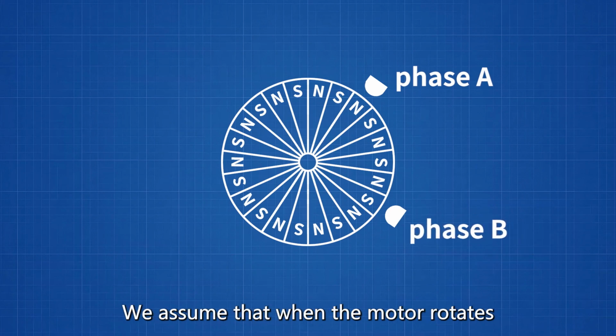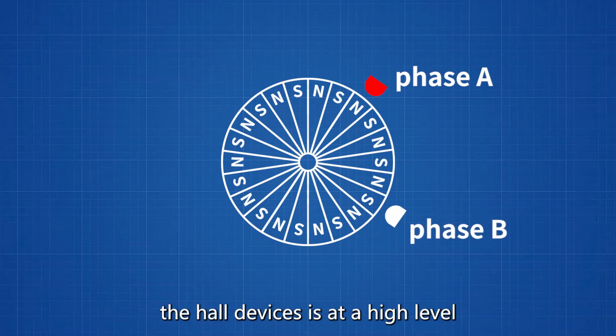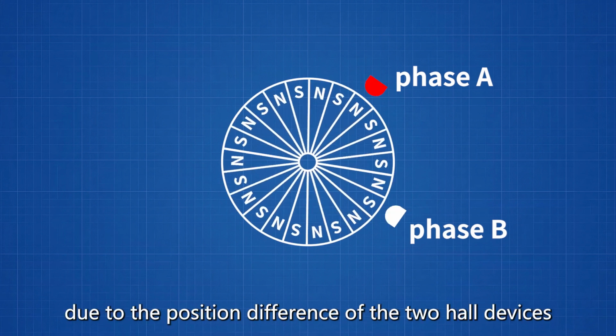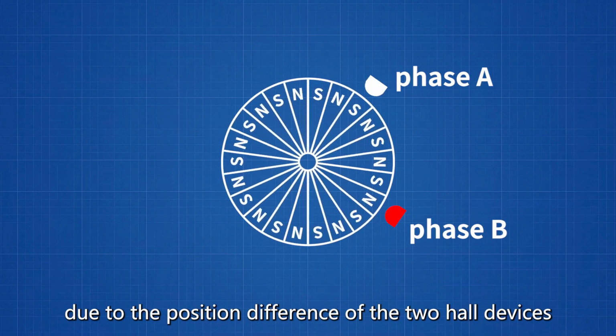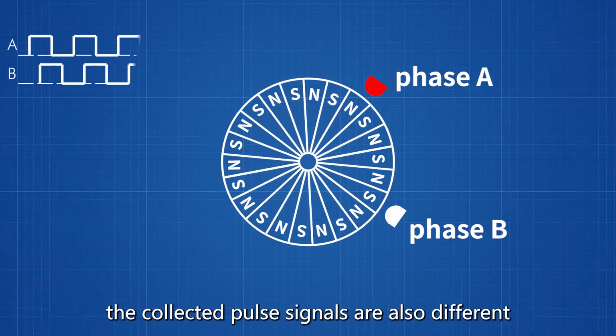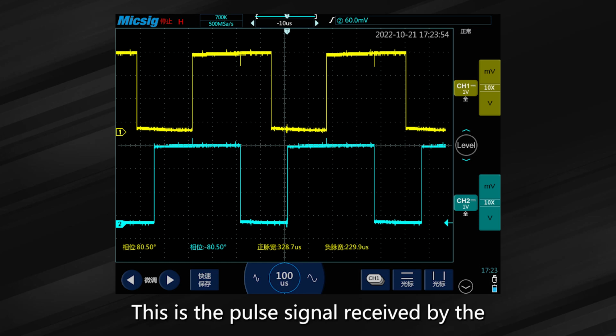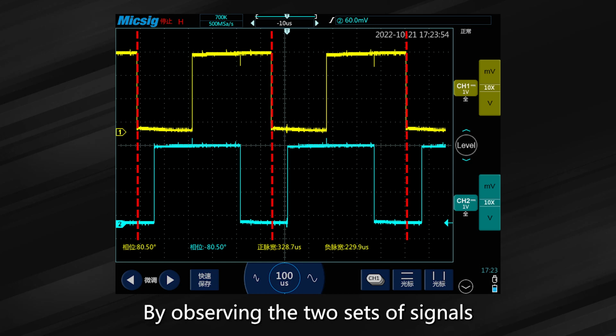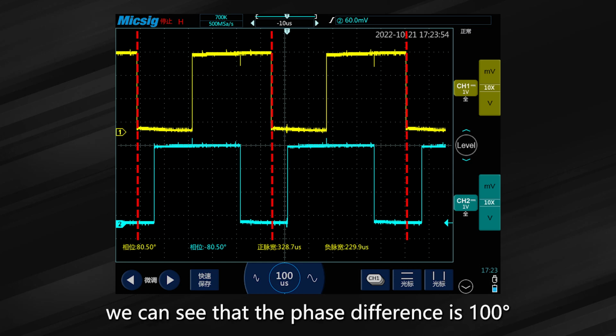We assume that when the motor rotates, the Hall device is at a high level when it corresponds to the N pole, and at a low level when it corresponds to the S pole. Due to the position difference of the two Hall devices, the collected pulse signals are also different. This is the pulse signal received by the two Hall devices when the motor rotates. By observing the two sets of signals, we can see that the phase difference is 90 degrees.